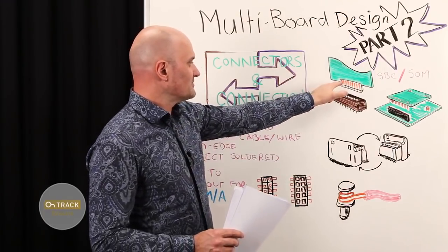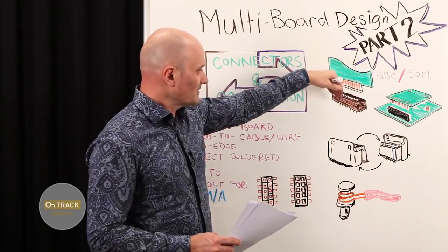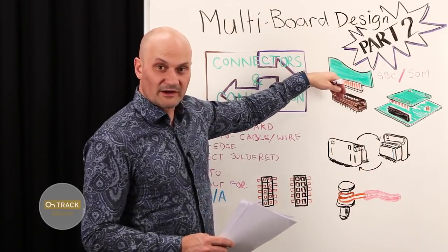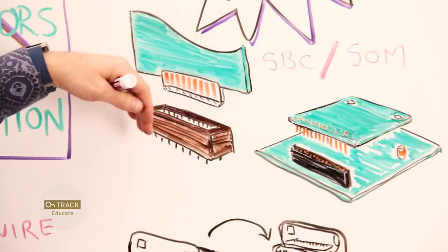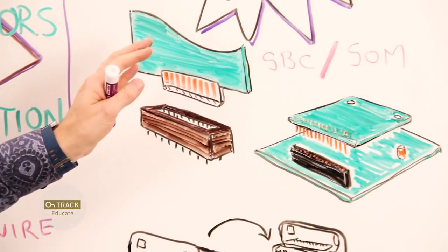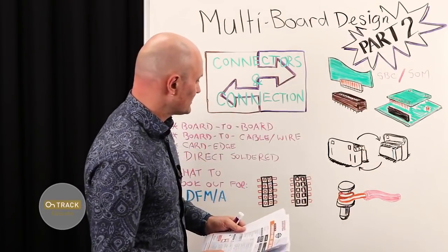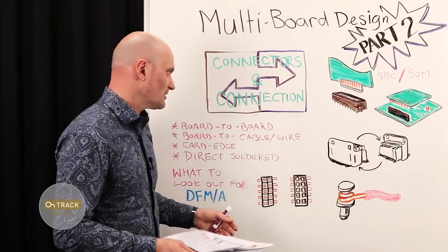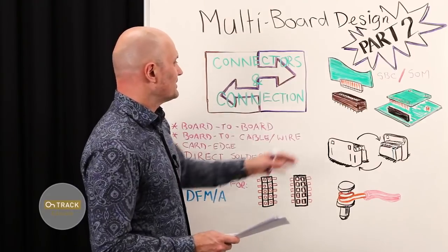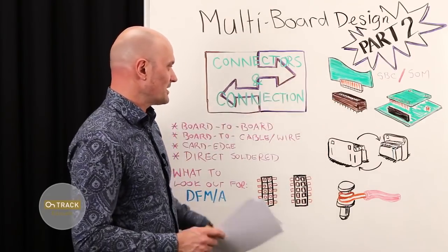The other advantage of the gold contacts is they're less likely to corrode, and when you get the physical insertion happening, any thin corrosion that may be there on the contacts is wiped away. So you get a pretty good connection. So it's generally pretty reliable. Again, only really suitable if you want something mounted at right angles to the baseboard.